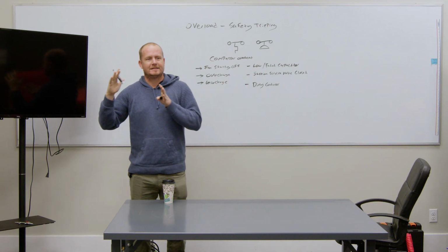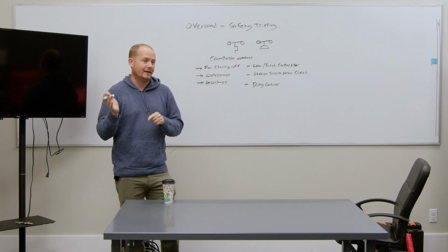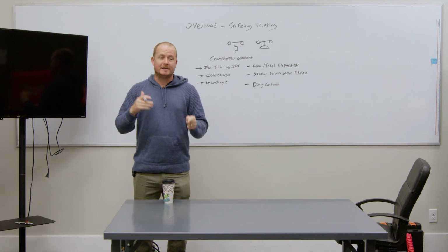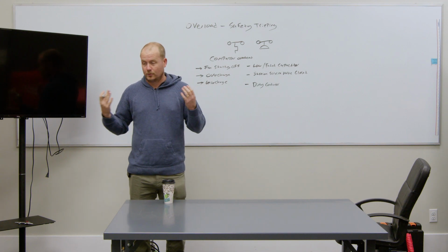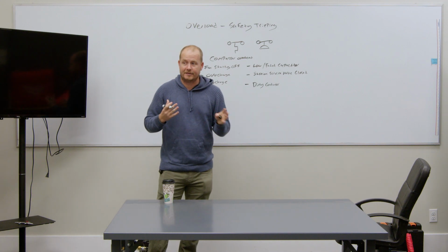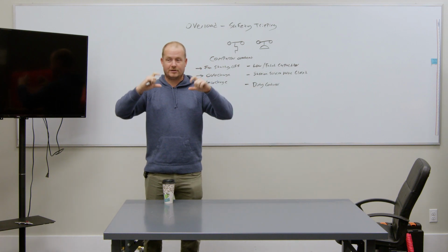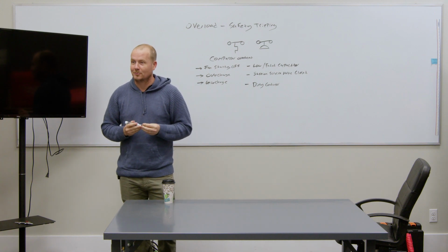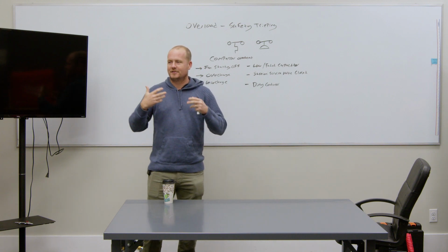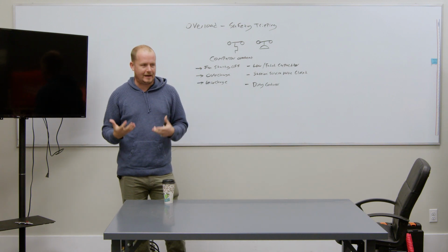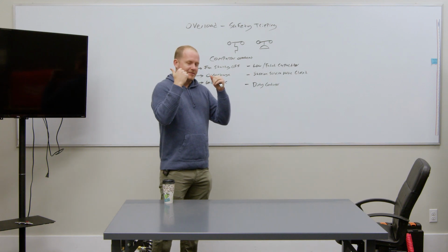So you show up, and if the LEDs are in the right order, the board is showing that you're out on high pressure lockout, but as soon as you reset power, it comes right back on. The defrost board comes out of lockout, now it's running. And when you test it, everything tests normal, like you would expect. Your gauges literally have a big message on it that says normal. All is normal. The robotic voice on your gauges shouts at you. You take all your measurements, you measure your amperages, and there's nothing really outside of what you would expect. But the message here is something caused that.